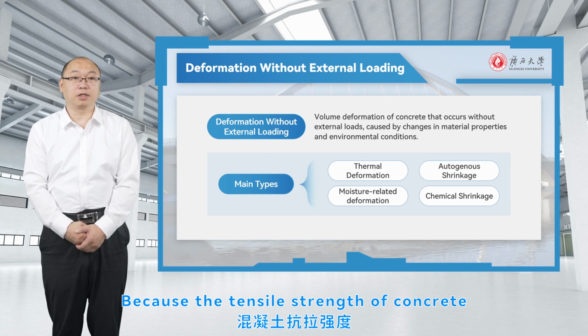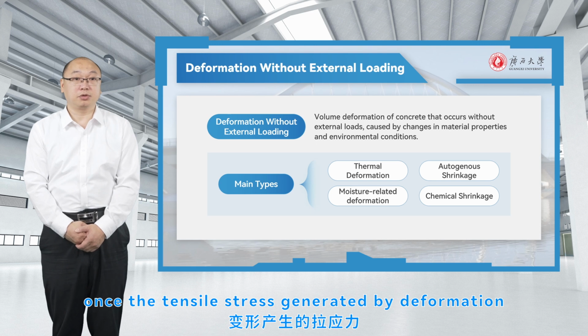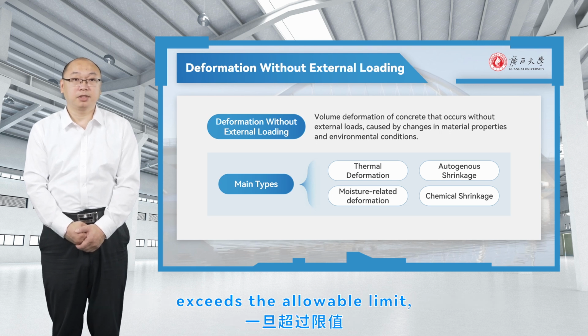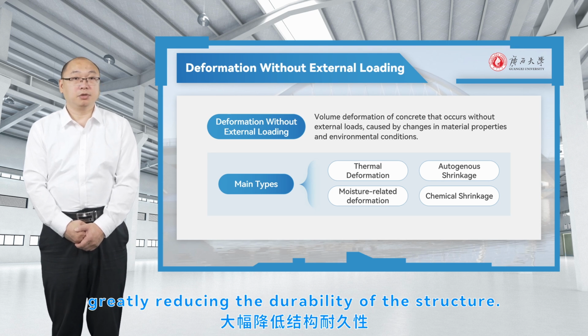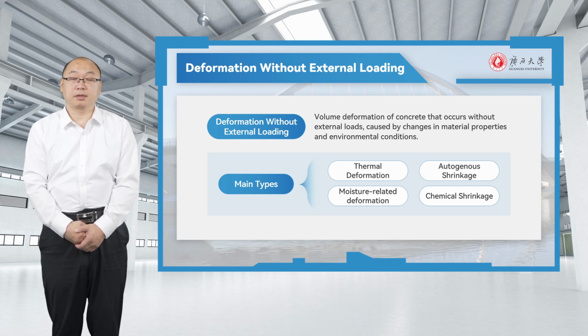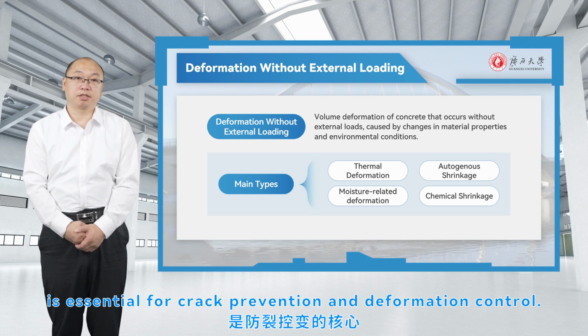Because the tensile strength of concrete is much lower than its compressive strength, once the tensile stress generated by deformation exceeds the allowable limit, cracking will occur, greatly reducing the durability of the structure. For this reason, studying deformation without external loading is essential for crack prevention and deformation control.